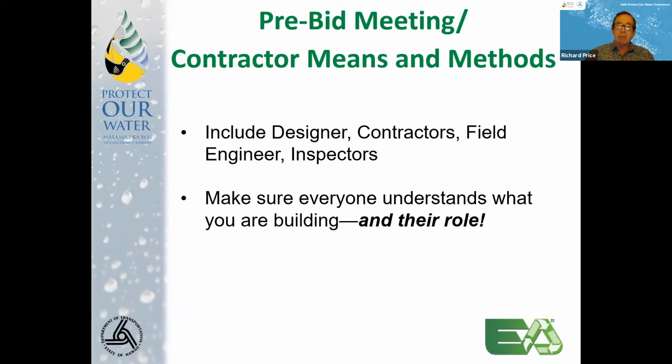The next step that I see is when we go to bid the job. It's important when we have a pre-bid meeting that we include all of the right people: the designer, the contractors, field engineers and inspectors. But also that we incorporate the stormwater controls, both construction BMPs and permanent BMPs if we have them on the project, as topics to be included in the pre-bid meeting and discussion, to make it clear what the expectations are for the